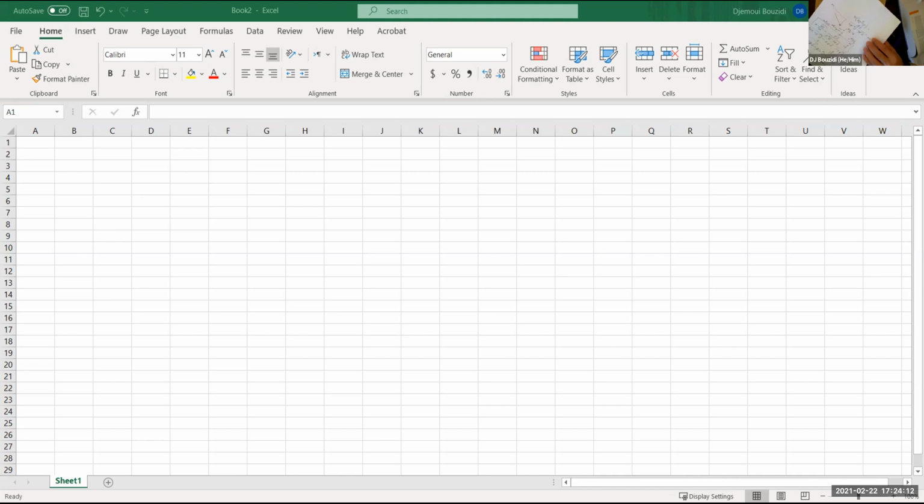So from this expression, I have some relationship between these rhos. Remember, A is 8 centimeter. So I have 3 over 8, where the units cancel, and I have in here 1 minus rho of the wood divided by rho of the object is equal to 3/8.